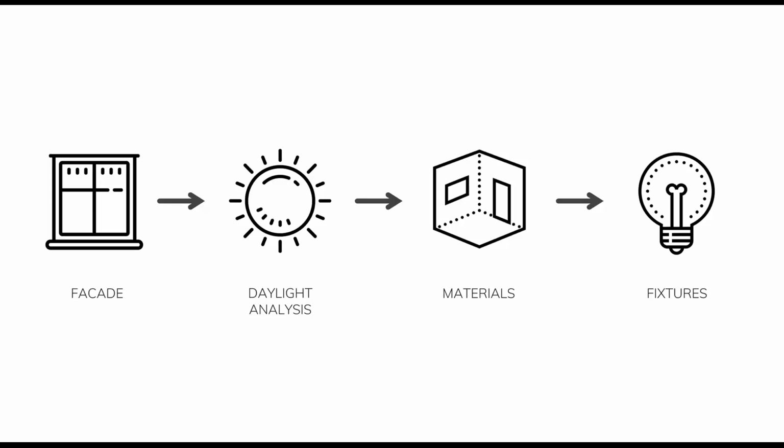One of the easiest, or most impactful, ways to respond to something like glare or lack of light is to change the materials. Maybe the material of the floor, maybe the material of the wall. If you have glare, you might pick a material which is lower in terms of reflectance. Vice versa, if you're in a low light environment, you might paint your walls white and really maximize the light bounce in there.